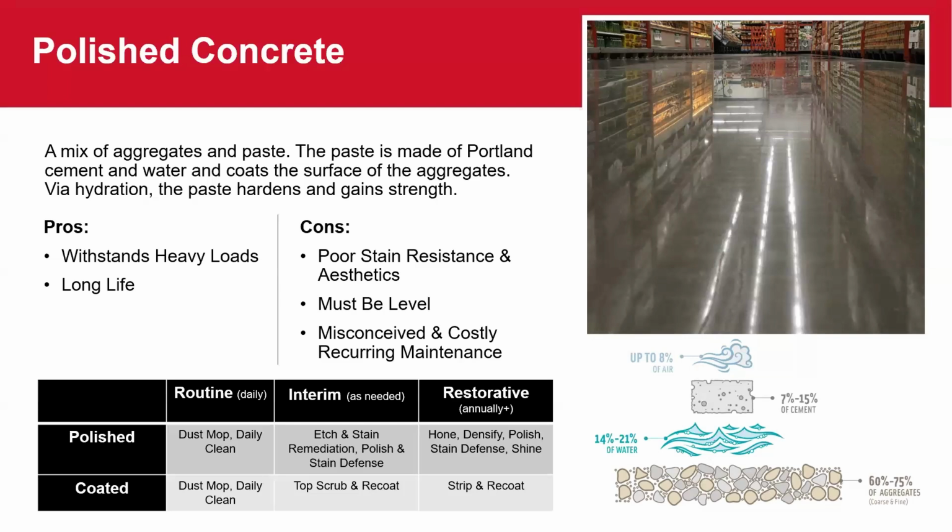And then we highly recommend a stain guard as well, not to resist 100% of the spills that go on that concrete, but to give the operator time to remove the fluid or whatever is causing that spot or stain on the concrete. Give them time to remove it before it does a deep etch or a deep stain. And if you're in grocery, as I mentioned, whether it be an acidic type product or maybe wine or olive oil or something like that, there's a lot of stains and etches to be remediated out of concrete floors.